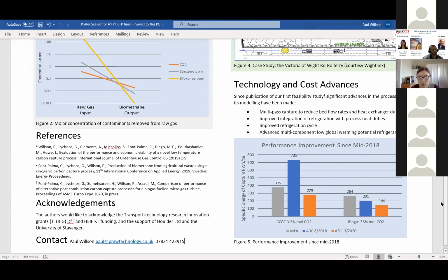The sulfur levels that remain are modest, and when we cool the gases, we reach the point where both the water and the sulfur content come out as liquids and are simply removed from the gases. The concentration of sulfur is not so high that it knocks holes out of every metal. It certainly needs to have some care and materials choice in that section of the heat exchange.